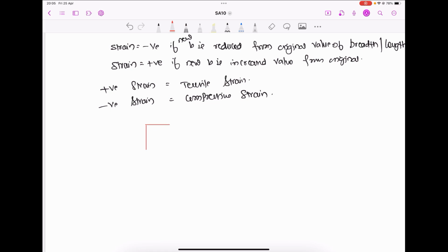Out of practice I have drawn this SFD and BMD correctly, but whenever you draw the SFD and BMD, these values will be positive whenever there is shear force like this. Shear force cannot be single; it will have two-way, and bending moment is like this. This is positive.